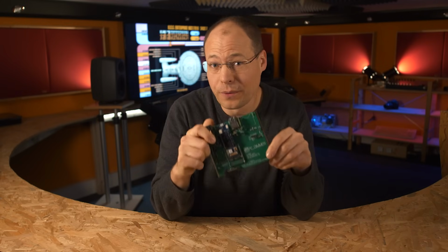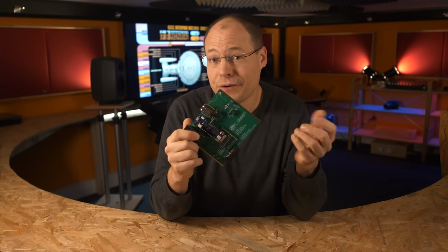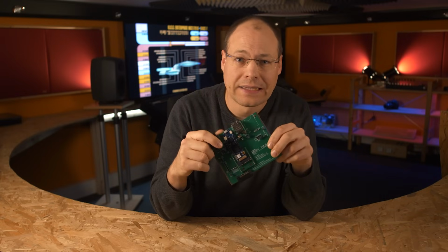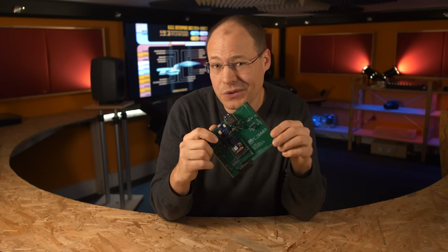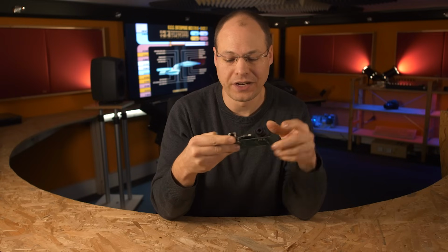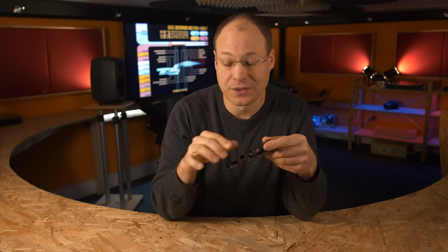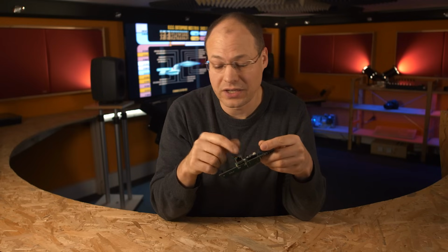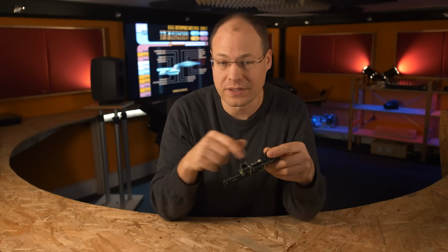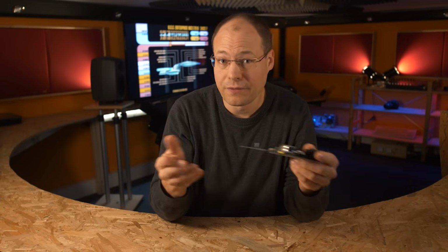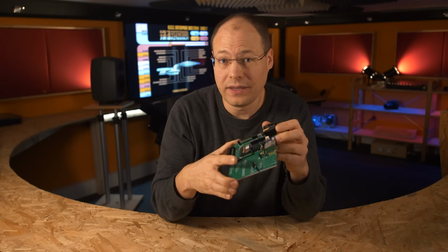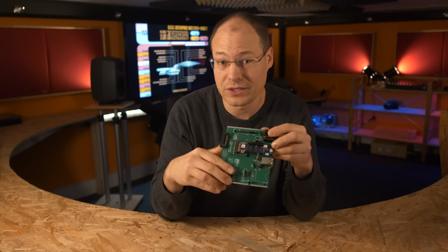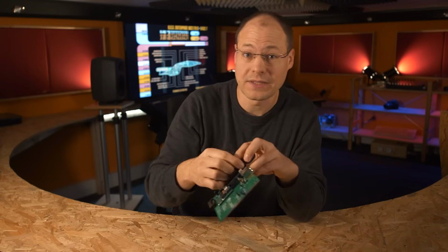Before I can test the new board with my X32, I first have to install all the firmwares in the individual controllers here. And maybe it's a good idea to do a dry run on the USB connection without the X32 connected to see if all chips are communicating with each other and if the Ethernet jack is working and the SPI bus, I2C bus and so on. For this I have to compile the Quartus project first and then upload the SAMD firmware together with the bitstream for the FPGA. So let's go.